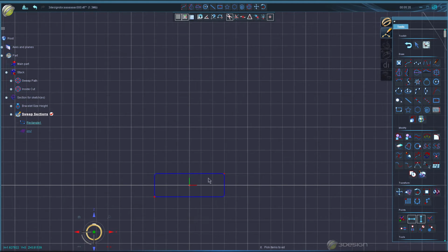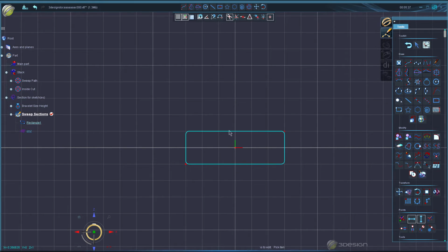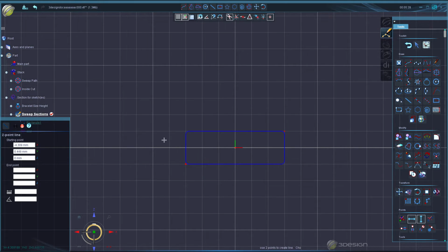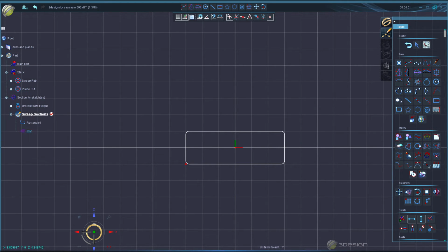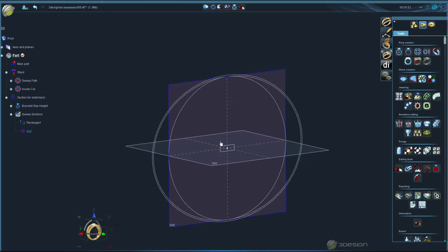Okay, so with that in mind, this is going to be the top of our bracelet, we want 1/2 millimeter depth in our cuts. So again, simple math, we just take 1/2 millimeter from our total, which is 2. We need to add 1.5 for our outside cut outline. So keep that in mind. We're going to go back and set that up.